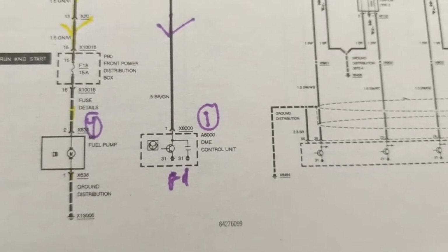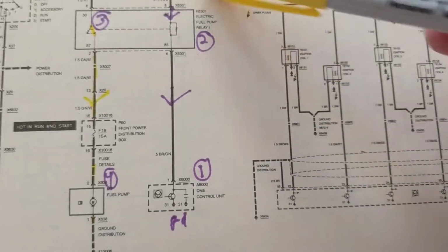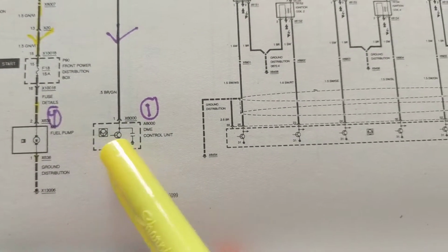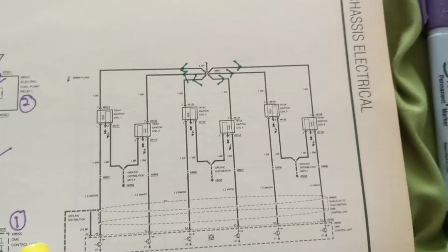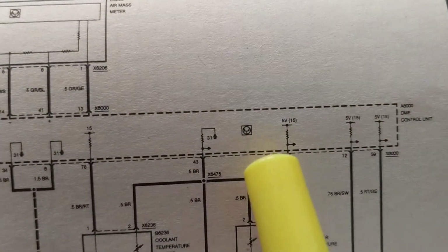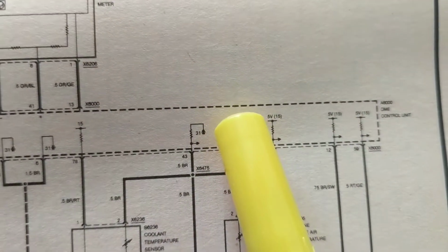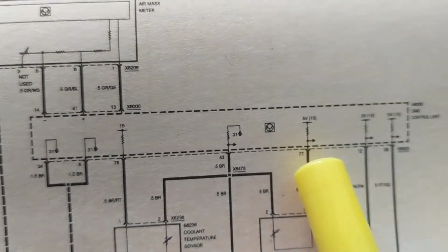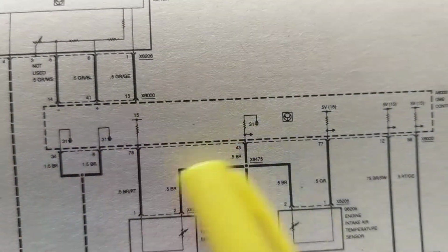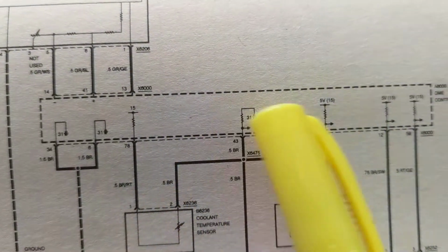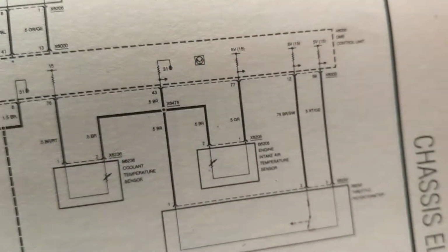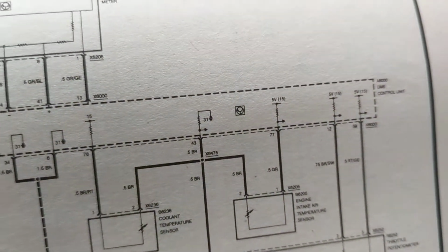What brought me to that theory? Let's say I'm trying to understand how to read a diagram. Well, first of all, how do I know there's a transistor in here? If you look at other modules, remember there was a transistor symbol right here, and this is a module. That's how I figured out transistors must be in here, and they must be used as on and off switches. A transistor can be used as an amplifier, as we spoke about.